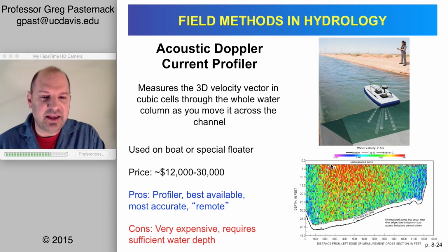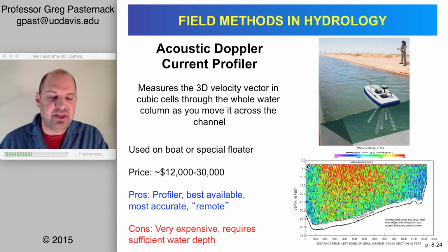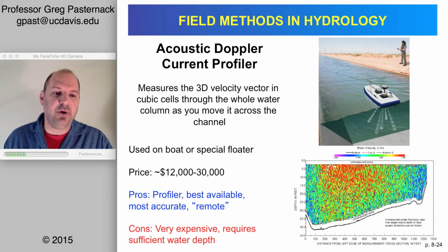I mean, for something like this, where you're blocking out, let's say 3 feet out of 30 feet, well, that's 10%. It's a meaningful loss, but it's not huge. On the other hand, if we were only going 15 feet, now you'd be losing 20% of your data. So you have to be mindful to purchase the right sensor with the right range and unmeasured blanking zone at the top.